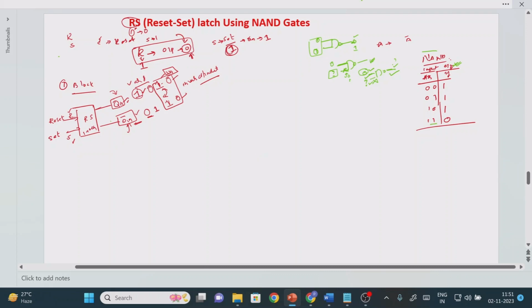See, the logic you have to understand here is this: this value is 0, then one more value here is 0. Either you can consider this 0 or this 0. Here one more value is 0. So from this, first we will concentrate on the output equal to 1. If we see the input values 0 0 0, just observe here: if any one of the input equals 0, then what is the output we are getting? Output equal to 1.